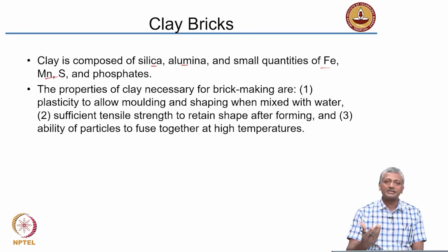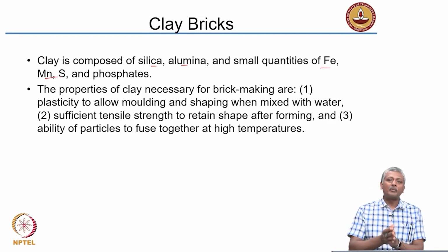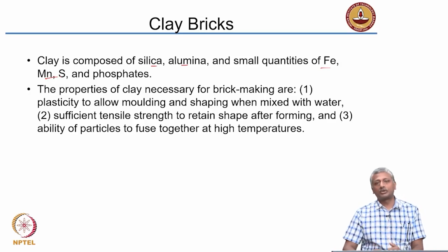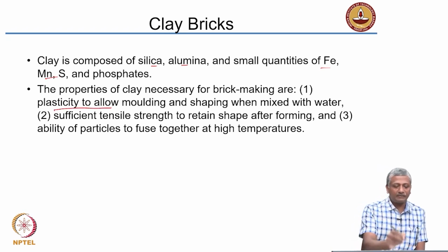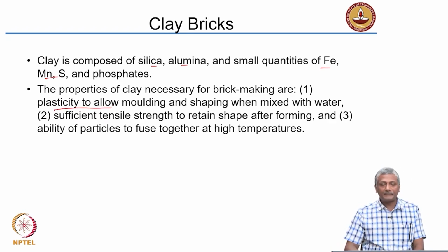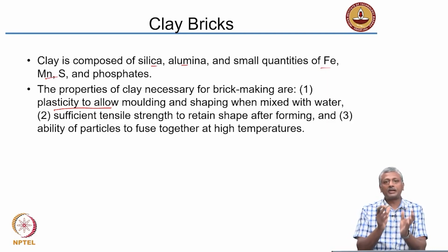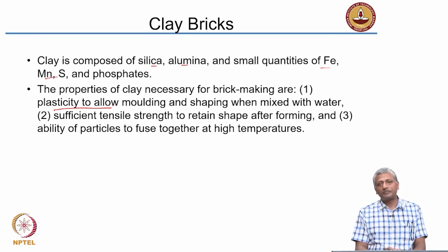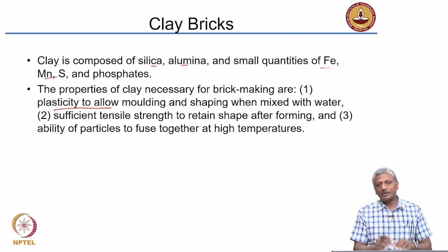Now, what do we do with this clay? As you all know, you played with clay as children. When you mix it with water, it has a nice pliability or plasticity. So you can actually start forming shapes when you mix the clay with water. So what you need to do is, you need to have that plasticity that allows molding, and you need to have the retention capacity of a shape. So supposing you have molded a particular shape, the clay should retain that shape after mixing with the water. So your water content should be just enough so that the clay is able to retain its shape.